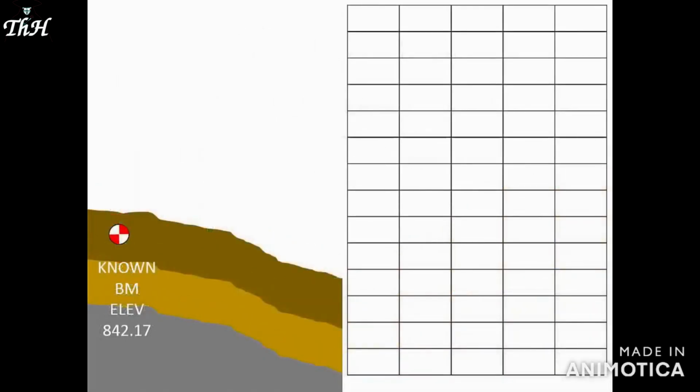For leveling, there is a standard format for field notes that tells the trained reader not only the measurements, but also the sequence of the measurement. The terms from the previous video, that is backsight, height of instrument, and foresight, form the structure in good field notes. Every measurement in our level circuit needs location information in order to be meaningful. The left column in the leveling notes is reserved for measurement location. In some types of surveying, the location is called a station. Well, here you can see the word station has been abbreviated to the letters STA.